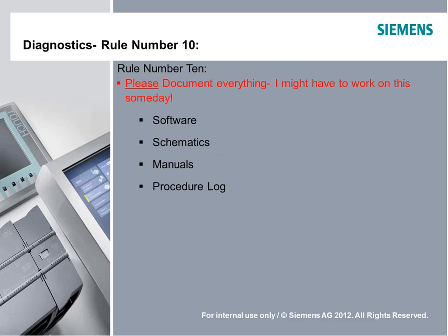I mentioned that most of the time software is not going to change. But oftentimes things will happen, like the machine originally shipped with a disk, and things get changed over time. It may not be the actual structure of the code, but it may just be recipe changes and those types of things. So if you're changing anything in the code or the set points or any of those types of things, document it, and then the next guy's going to have a pretty good idea of where to go.